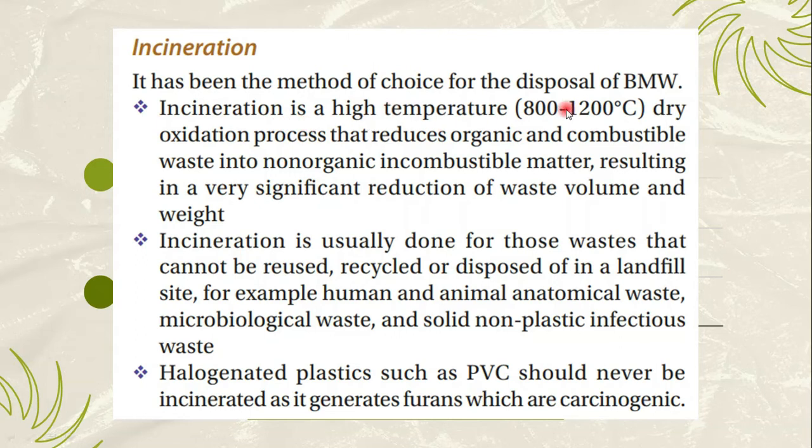Incineration is a high temperature, from 800 to 1200 degrees centigrade, dry oxidation process that reduces organic and combustible waste into non-organic incombustible matters, resulting in a very significant reduction of waste volume and weight.